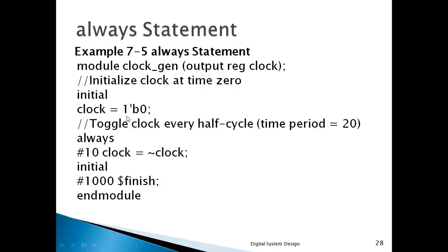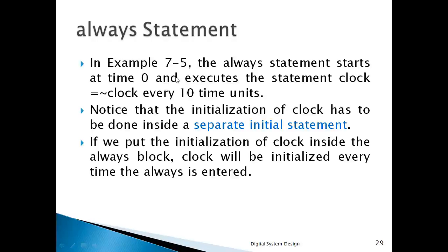So initialization will be used in the initial block. Here this detail is given that if we put the initialization of clock inside the always block, clock will be initialized every time the always block is repeated.